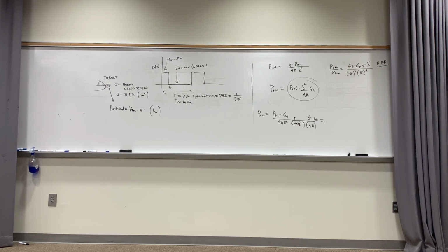Well, with a magnetron, you basically hit a cavity that has a magnetic field with a burst of electrons. And what they do is kick it, in a sense, and it creates electromagnetic energy that's going to bounce around and have a certain characteristic frequency, the resonant frequency that I want. That energy can be sucked out by a little threaded antenna in there, and then it rings down.